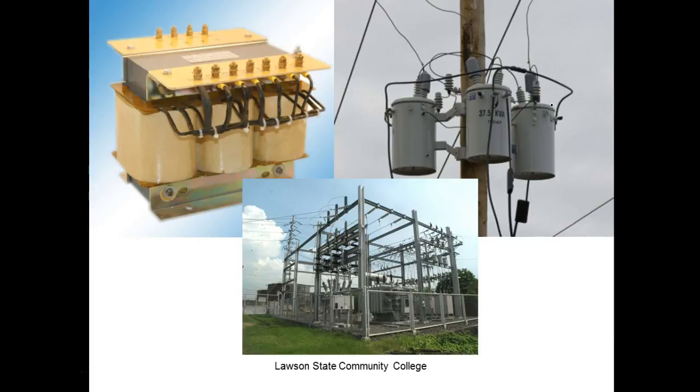So these are three-phase transformers. These are substations. What's the function of the substation? Change the voltage. It's either going to step it up for transmission or step it down for distribution, right? So extremely high voltage for transmission, a lower voltage for distribution. Usually on the power lines out by your house, it's a couple of thousand volts. Still very dangerous. A couple thousand volts. And then you'll have a transformer out there close to your house.